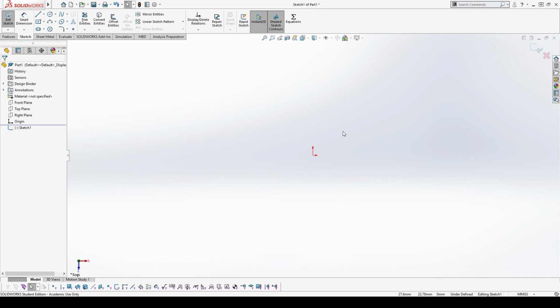I can't remember if I covered this in the second or first half of last week's session, but the S toolbar is very, very useful. Actually, I believe you guys can't see it. By pressing S whenever you're in a sketch, if you are following along within SolidWorks, it brings up a little toolbar of a bunch of more common commands. So you have your line tools, rectangles, all that kind of stuff pops up right next to my cursor. Seeing it now in my preview, it looks like it's not popping up, but I'm still trying to figure out how to stream a display. OBS doesn't like me, but I guess I'll just hover over here.